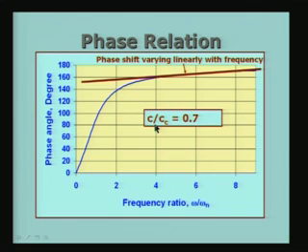If I had a case where it was 4, and 3.5 times 4 will be 14, you will see that it would have followed faithfully, because it is in the linear part of the curve. In this case, because the first point is actually in the nonlinear part of the curve, there is a net phase difference, and that corresponds to 0.3252 radians. It will all be a plus 0.3252 radians in the present case we have talked about.